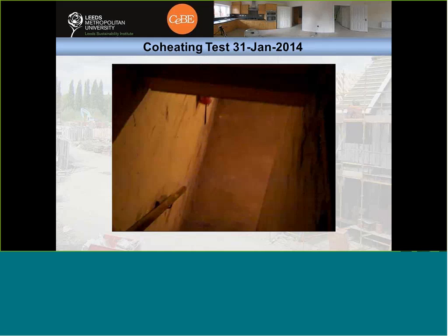Here I show you a co-heating test setup in an investigated dwelling. So you can see the heaters that are dispersed throughout the dwelling to heat up the indoor environment. They are controlled using thermostats. We also have ventilators to mix the indoor air to have as homogeneous a distribution of the temperature throughout the dwelling. And last but not least, we have the sensors spread throughout the dwelling to monitor the variables which will serve as an input for the data analysis.